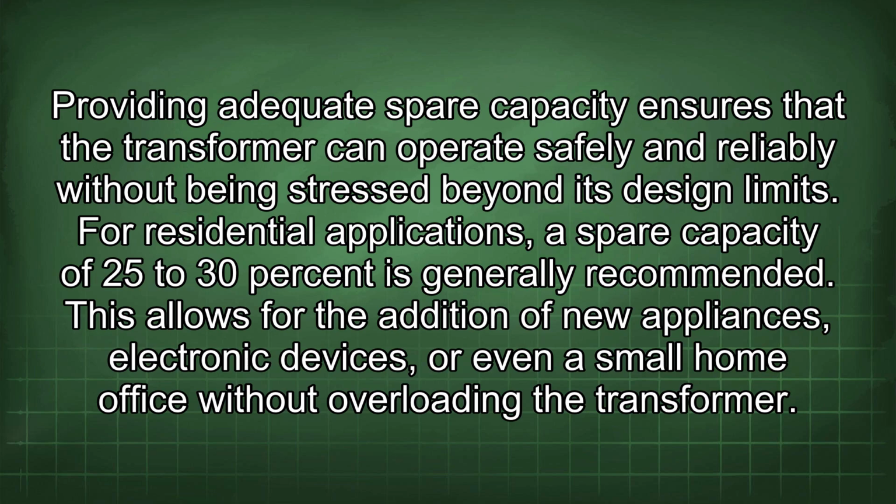For residential applications, a spare capacity of 25 to 30% is generally recommended. This allows for the addition of new appliances, electronic devices, or even a small home office without overloading the transformer.